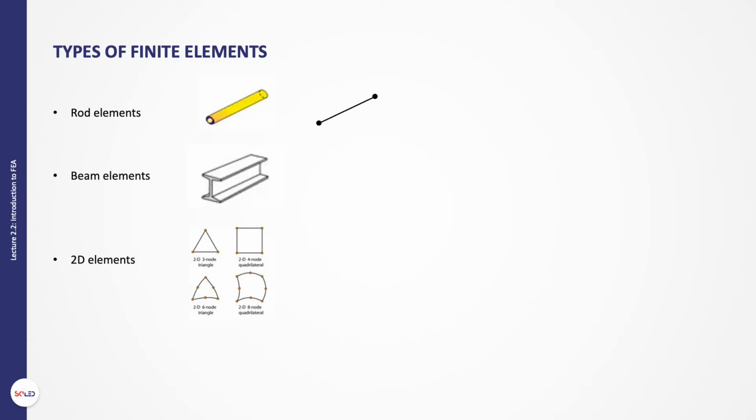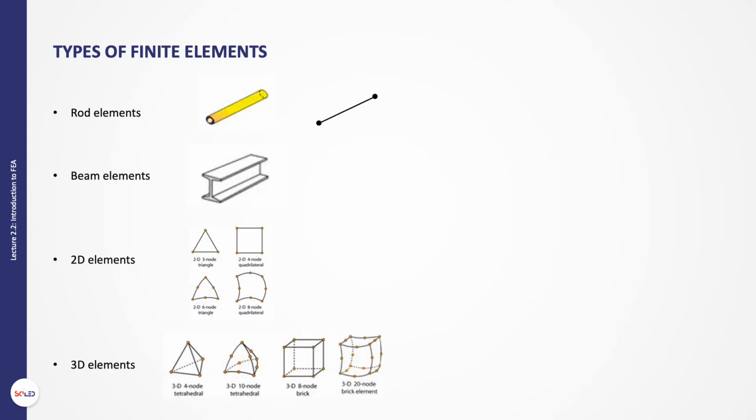2-dimensional elements are used to model surfaces. If the surface also accepts bending forces, then we use shell elements, which are the same as the 2D elements, but they also accept bending forces. The only data needed in 3D analysis are the elastic properties of the material. In addition to the above types of elements, several other elements are available in FEA commercial programs for more specific applications.